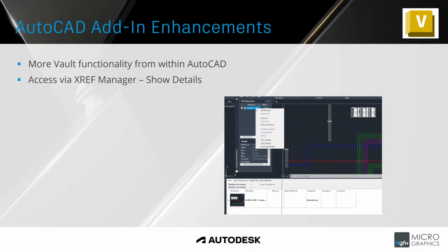Vault will manage everything. So as you can see at the bottom over here, we've got history, uses, where used, change order, and bill of materials. Probably the biggest thing over here is the bill of materials. You can see the drawing at the back is an electrical drawing. So if you're using AutoCAD Electrical in conjunction with Vault, one of the things you can do is create items and create a bill of materials out of